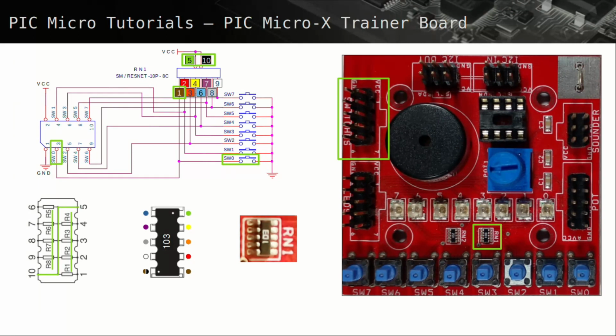The switch 0 is also connected to pin 3, with a normally open contact. The other contact of the switch is connected to ground. When switch 0 is pressed, the whole circuit is taken to ground or sunk. The switch circuit is said to be active low. When pressed, the pin goes low, else it is pulled high.